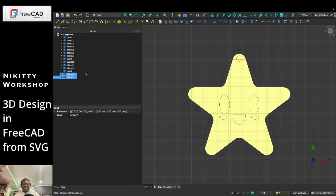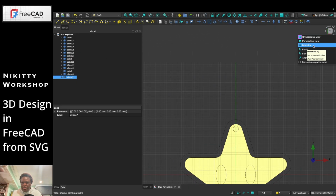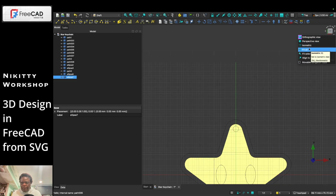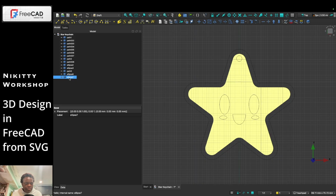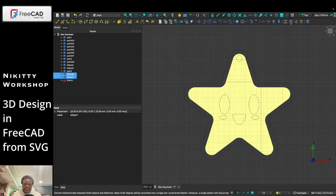I'm creating the sketch together to make it one object. Let's see, isometric. And then I'm going to fit all. So we're going to select these two, and then you want to hit this little symbol here that says draft to sketch. So you're going to press that.